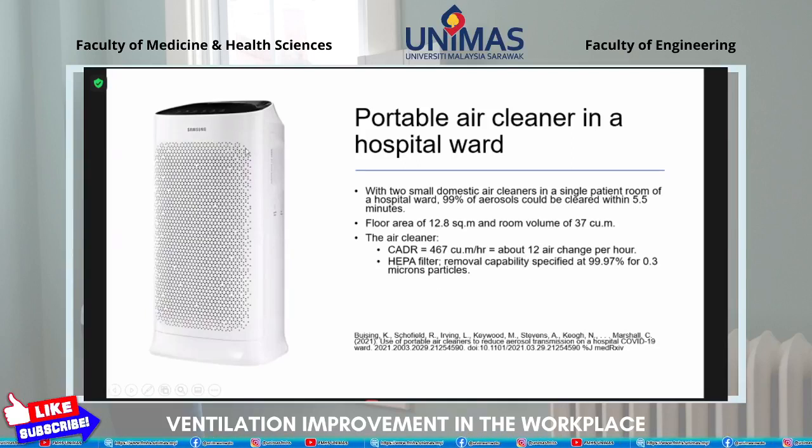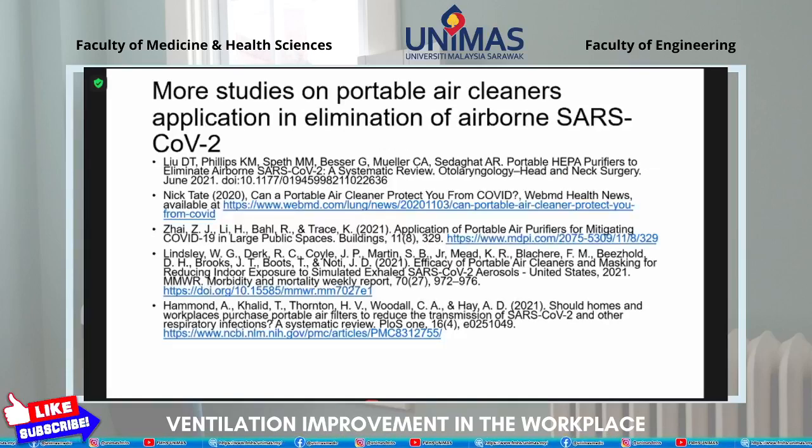And then this air cleaner is using the HEPA filter, which is capable of 99.97% removal of the 0.3 micron particles. So basically, this is H13 HEPA filter. So these two can hopefully help answer the question of Miss Grace just now about the use of air cleaner, whether it can actually reduce the aerosol inside the room or not. But again, there are more studies that you can have a look into later.